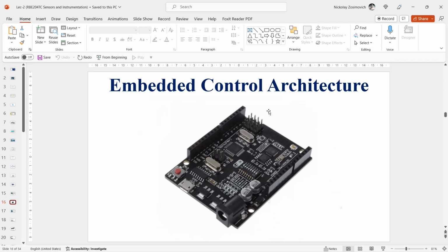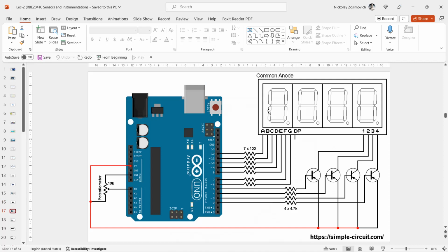For embedded sensing, one of the most relevant devices in the controller is the ADC. The board that is used has a 6-channel 10-bit AD converter, which in the normal configuration, with a single channel, can take a sample in 100 microseconds.